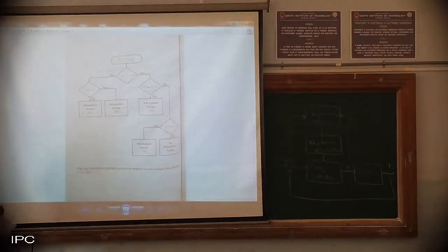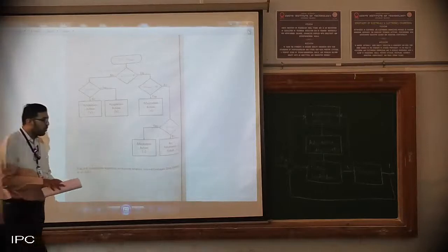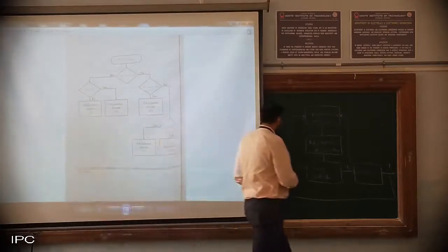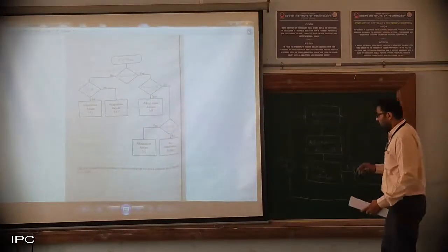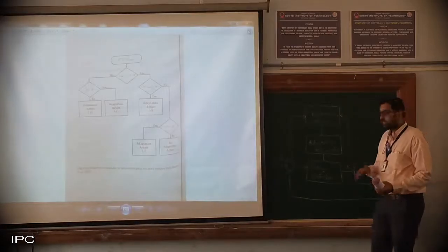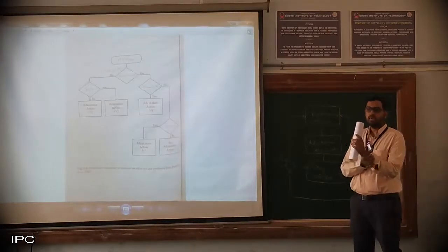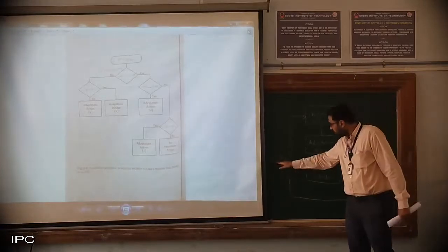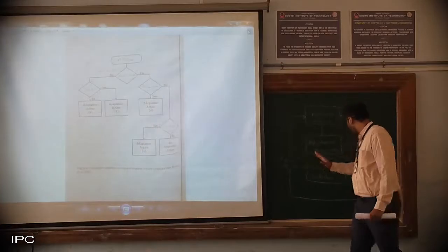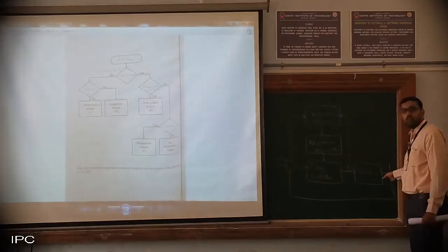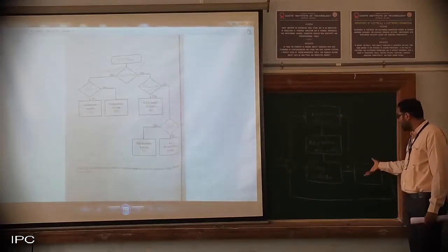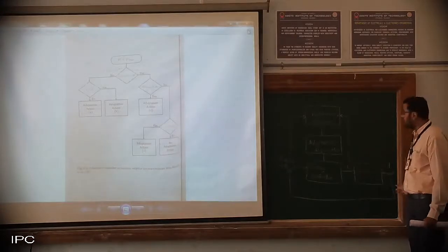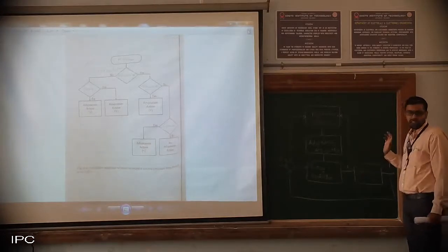Before going ahead with that part, let us understand the block diagram of what exactly we are going to do here. When we are using this, we require a reference. The set point is nothing but the reference value. For example, we require a speed of 1500 rpm, so my reference value will be 1500 rpm here, and this is my actual output. Let us say the process is basically a motor. The motor is rotating at 1480 rpm.